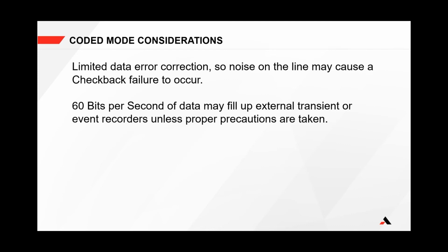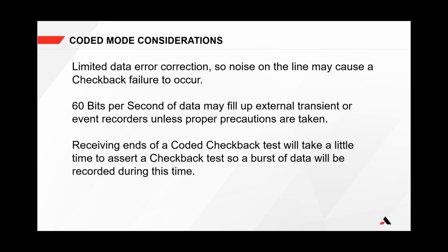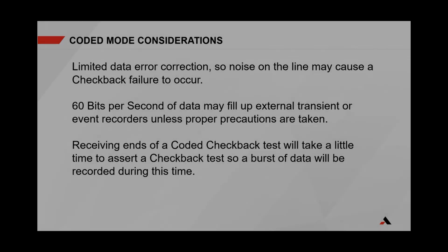to be designed into the station design and requires a recording device that has an input for disabling event recording while active. Also be aware there's a small delay for the receiving ends to assert the output, as they first need to determine if this is checkback. So at the remote ends, there will always be a burst of data recorded before the output is asserted.